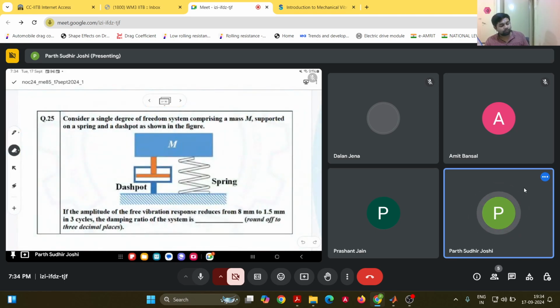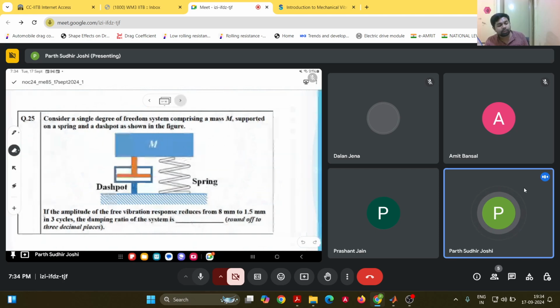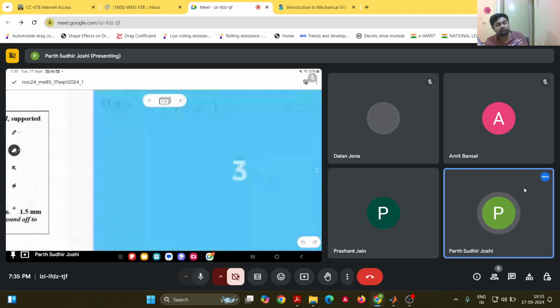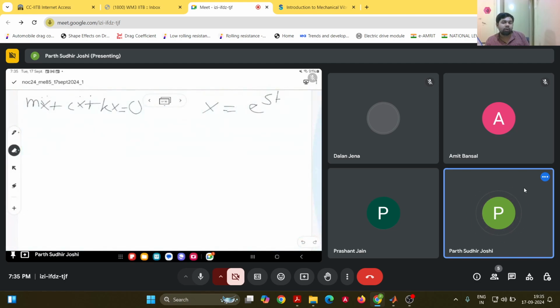First of all, the fact that it is given that there is a vibration, and there is damping present in the system, means that the system is underdamped. So then you actually don't need to do this. You can just pick up that particular form of the solution.